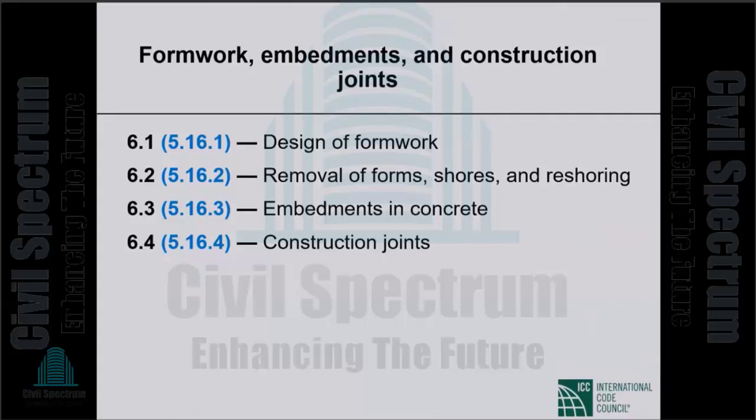Shores are the posts and things that support the forms. Reshoring is you remove the forms when concrete has gained sufficient strength, but at that point you still have to keep the slabs supported. So you remove the shores to remove the formwork, but then you reshore. You put the posts back, supporting the slab directly.